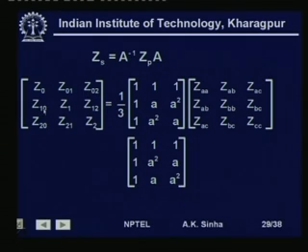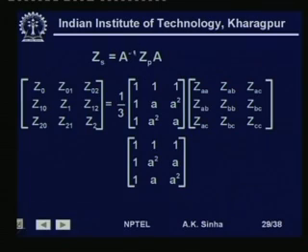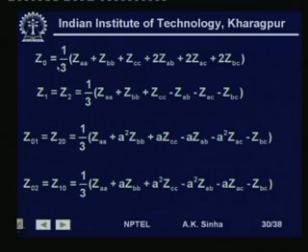Similarly, positive sequence to zero sequence, positive sequence and positive sequence to negative sequence. So, we are writing the 9 terms for the 3 by 3 matrix, including the coupling terms between the sequence networks. So, if we do this A inverse Z P A, then we have 1 by 3 this matrix which represents A inverse, this is Z P and this is A,